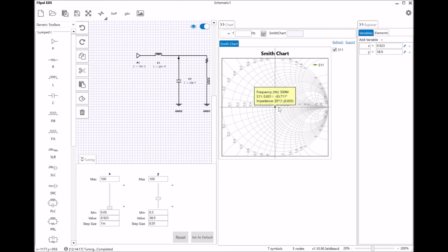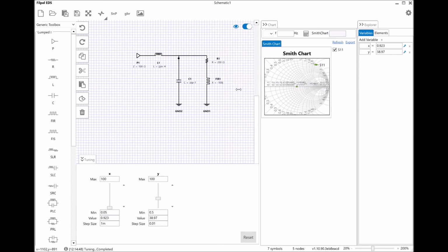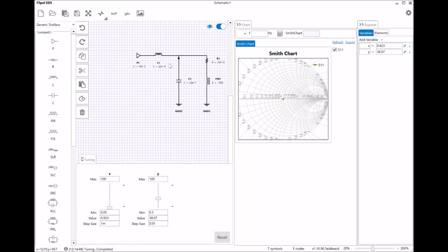So now it is in the capacitive region. So if I want to bring it up to 0, then I have to add more inductor. See 0.002, 0.002 still, 1 more, still, yeah, this is increasing to 0.001, 0.001 still, yeah. So now you get your impedance matching done, which is very useful, because when you add the